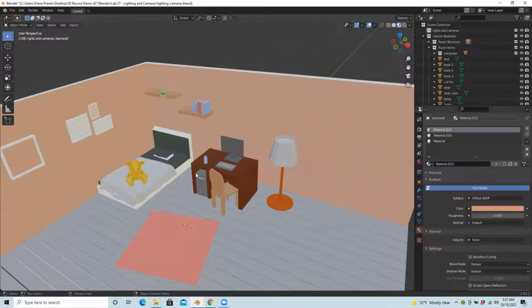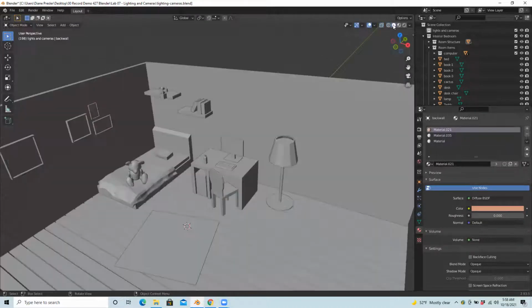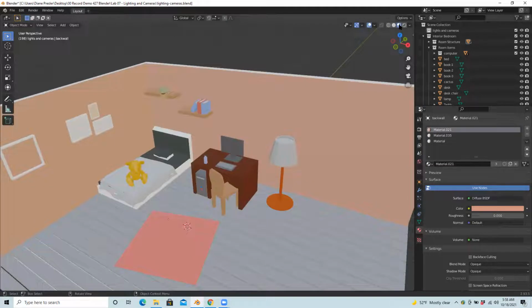Right now everything looks kind of flat and it's previewed. Up here I'm previewing materials. If we look at the little icons in the upper right corner, I want to remind you that you can change how you're viewing your Blender file. For example, I can go into wireframe view. I can view things just shaded. That's usually a good view for modeling objects. And then most recently, you've learned to go into our object properties and learn about material properties. And we're in the material view.